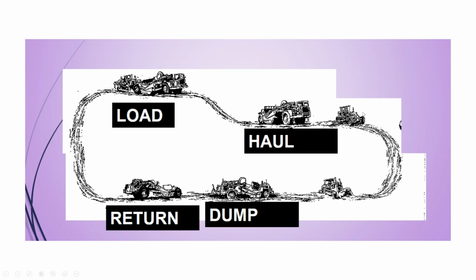And here, does anyone know what this cartoon is? It's a motor scraper. What is its job? To maintain the haul road. And we're going to find out that maintenance of the haul road, or the condition of the haul road, will control our production. It makes sense. If you don't have a good road, then your vehicle can't move as quickly as it possibly could, and therefore we will see some drop in efficiency.